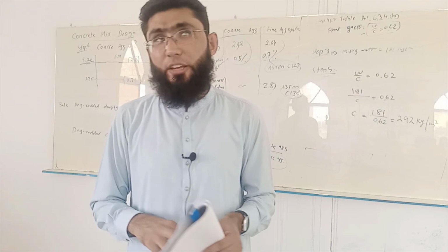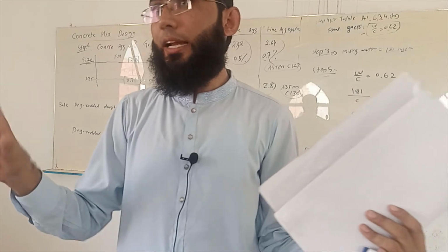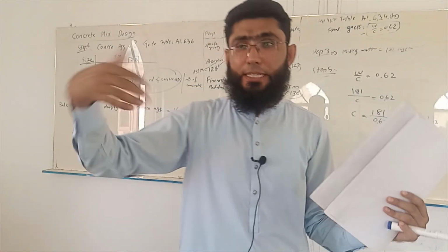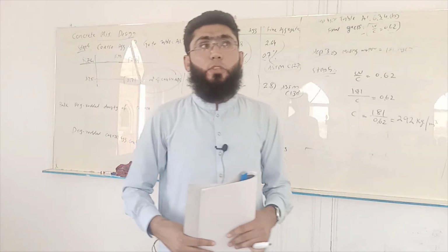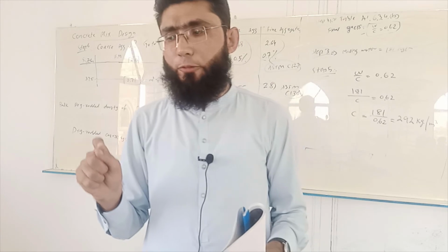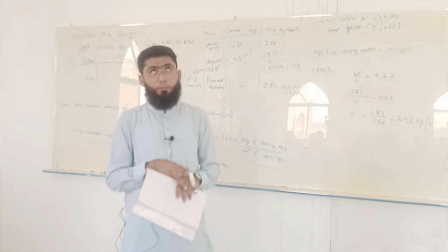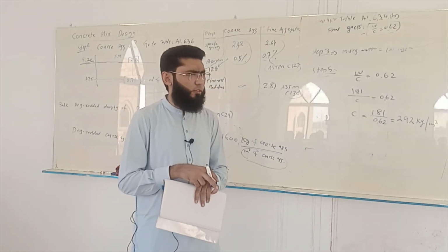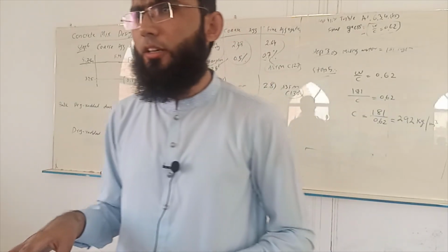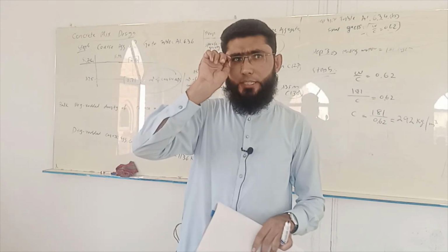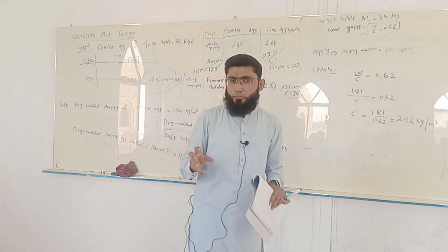Okay, so when you say 2300, it refers to the hardened concrete in which water is evaporated and it's slightly lesser. But when we talk about fresh concrete, it is slightly higher because the water is not yet evaporated. So we call it the fresh density of concrete. And there is a standard for finding that. I'm guessing it is C30 maybe or C130, I have to check this, but there is a standard for it. Very simple test. So the fresh density of concrete, if you can guess that value.